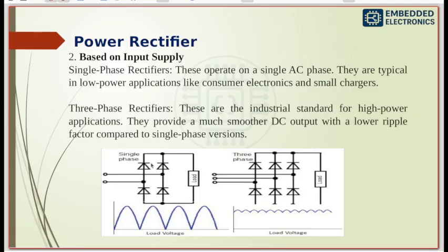In the second half cycle, electricity swaps and comes in from the bottom wire. This is during the second half cycle. And the other two diodes steer it, so it still goes down to the load in the same direction.